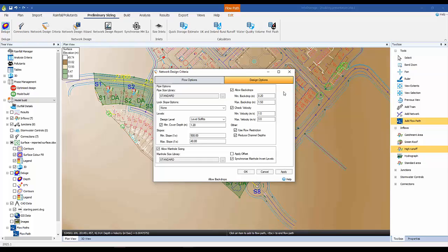In some steep catchments, it's difficult to know what the alternative is. You have no alternative other than to lay the pipes at very steep slopes, which is going to create some high velocities and therefore the potential for damage within the sewer system. So sometimes you need to use backdrops in certain situations, and if you do, there is now an emphasis on those. You can put them in and it will be designed to those required settings that we have in here.